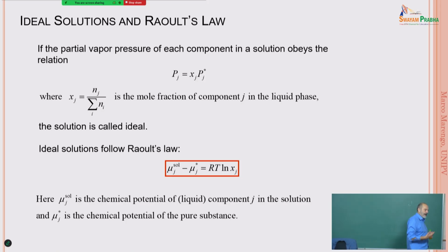How can you check how much gas is inside? Well, you need to consider the fact that when you have a second component inside, the saturation pressure doesn't correspond anymore to the saturation temperature for the pure fluid. So if you are considering a given temperature, you should expect a given pressure. But if you have dissolved gas inside, you're going to find a different, lower pressure.